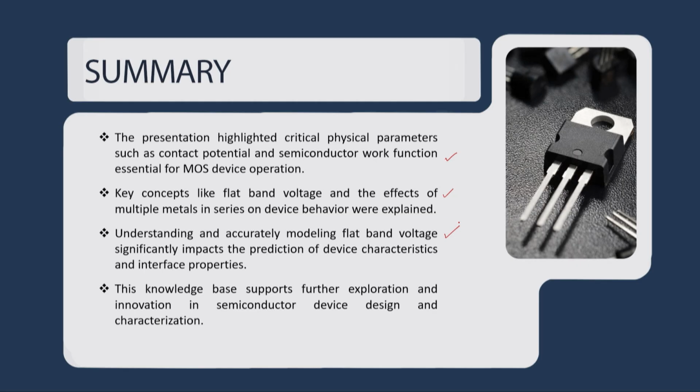We have seen that we have a basic fundamental block as a layered structure which is called a MOS cap. So, I have a layered structure which is metal, oxide and semiconductor. This acts as a capacitor when we connect a voltage between G and B, which is nothing but V_GB. We have also seen that the contact potential developed between gate and body causes a charge pile up in the semiconductor, which we do not want, right.